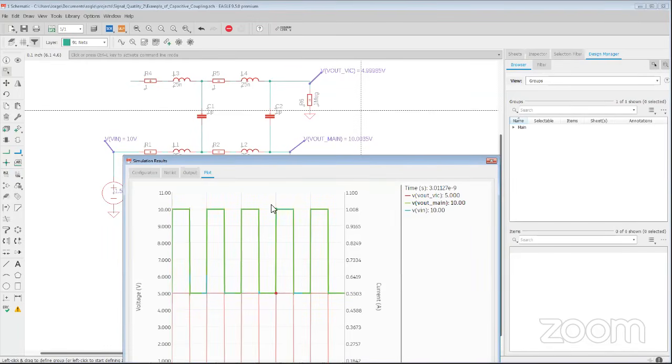Okay. And again, I do need to mention I have glossed over some stuff here. There are other terms, but the term often used is parasitics. Some people don't like it because parasitics implies the idea that they're unintended or they shouldn't be there. But the reality is that they are there, and if you don't take them into account, you can't predict the full behavior of your circuit. So this is just a really simple example of capacitive coupling.